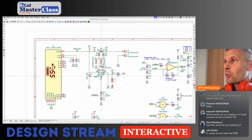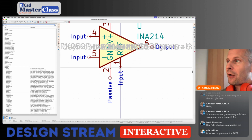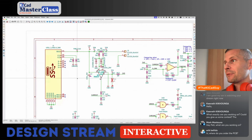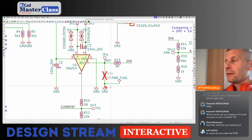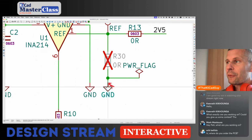My symbols are usually created in a way that the negative power, the ground, is marked as passive to avoid half of the similar errors. But sometimes the power flag is still missing, because sometimes I think even the ground port is set as power input.